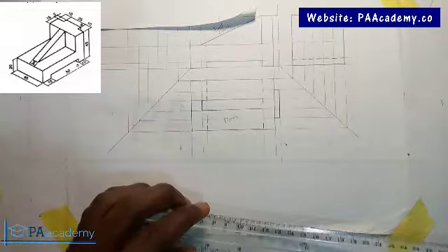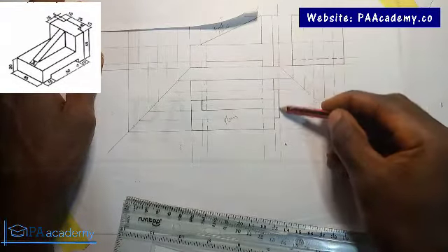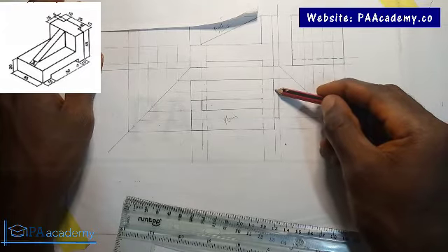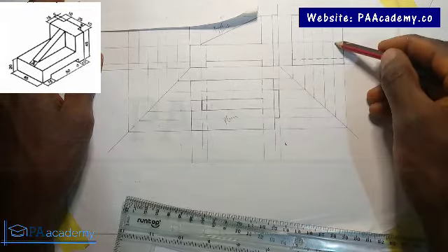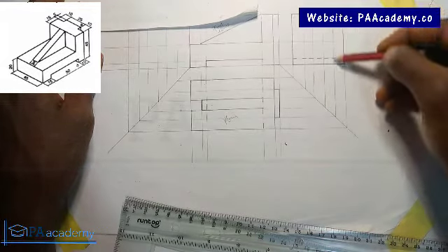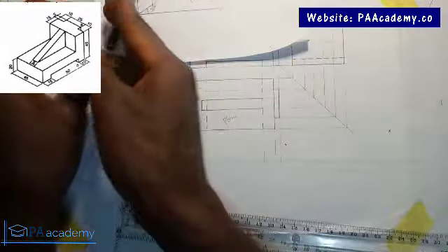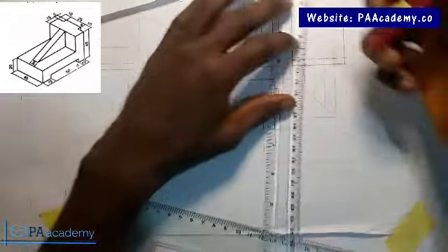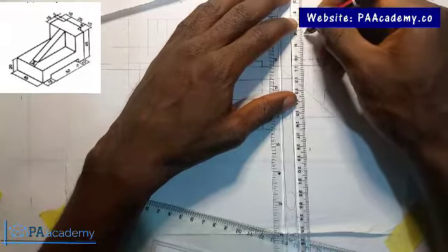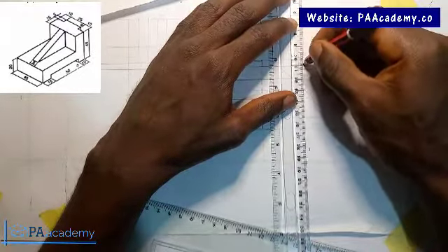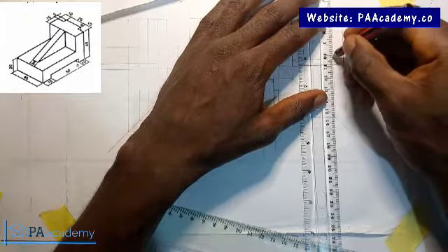And also if you just want to confirm, if you are looking at it from the top, when we are drawing this top, you can see that this part here is the edge here. This is the line that extends here and continues here. It's the same line that extends here and continues here. So that's just letting you know that this is the line that represents this part on the side view. Exactly. So with short dashes, so short dashes for hidden details.